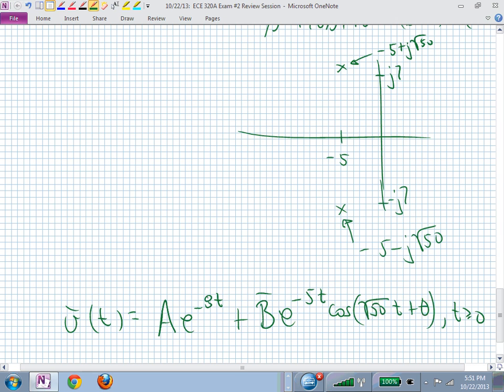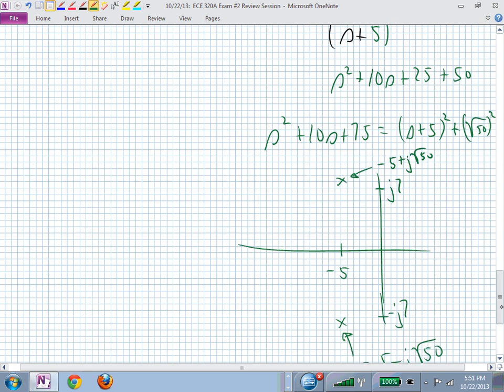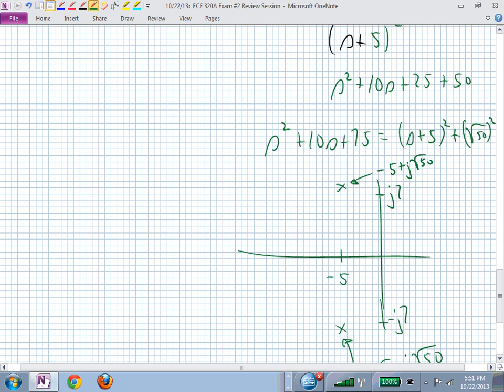So what you're keying in on are those poles in the denominator. And if they're complex, then you need to find how far into the complex S-plane they are with the real part, and that gives me my decay. And then how far up on the imaginary axis are they? That gives me my damped frequency.